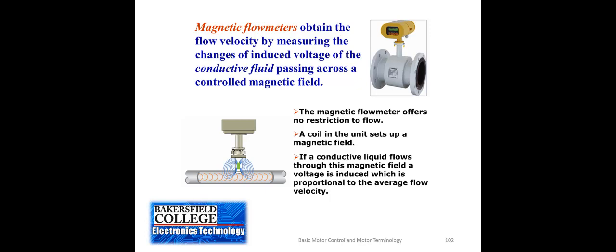There is another one that's called a magnetic flow meter. Now it kind of seems like magic how this thing works. It makes a magnetic field, and that causes the molecules inside the liquid, as long as the liquid is conductive, to align electrically.